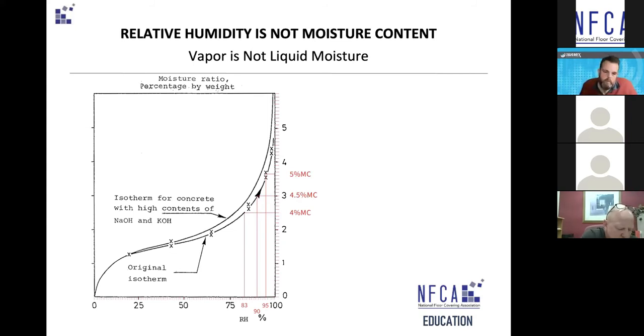Yeah, well, the whole idea is that moisture causes problems, and pH, alkalinity. So alkali moisture is your biggest concern. We don't see that there's only one way to test. What we feel is that you need to know what you're testing, because there's a misconception out there that when you measure the vapor, you're measuring the moisture. So if you imagine how much moisture concrete can hold, especially if it's a permeable concrete, it can hold a lot of moisture.